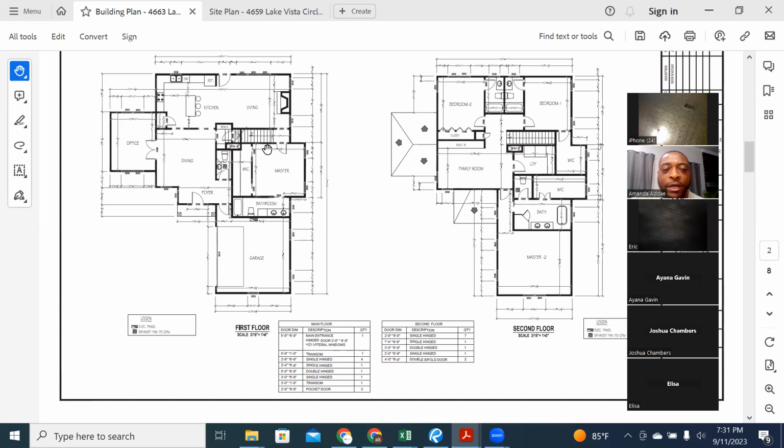So if a regular architect drew these plans for you, you might just have the plans without the foundation slab having all those interior grade beams inside. Okay. I've had a plan before where the engineer put like 4 rebar number 4 wires and has some number 5 wire. And everybody agreed it was overkill.